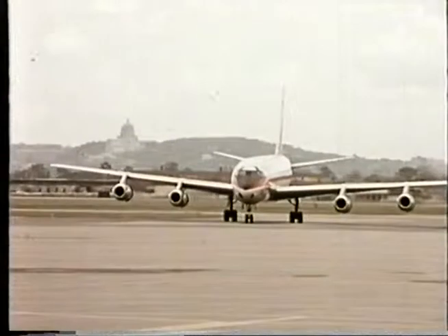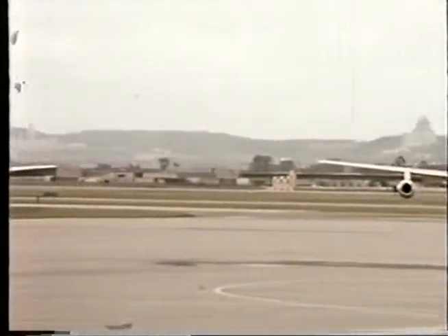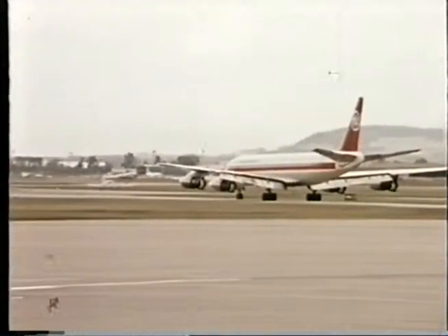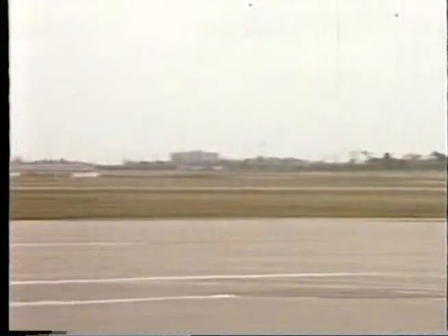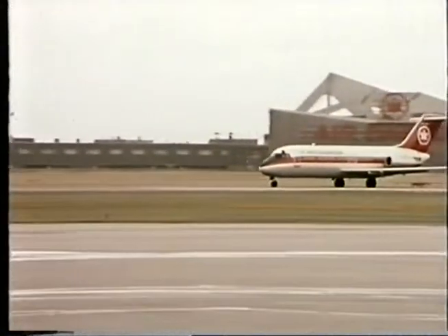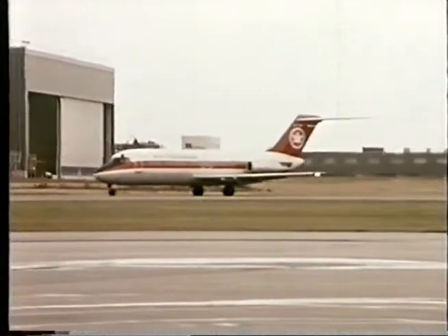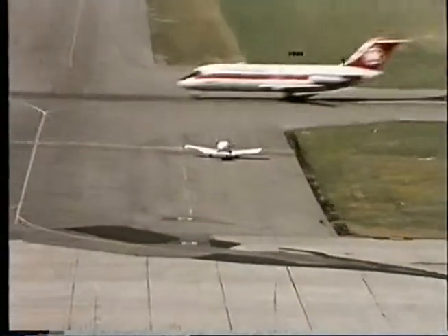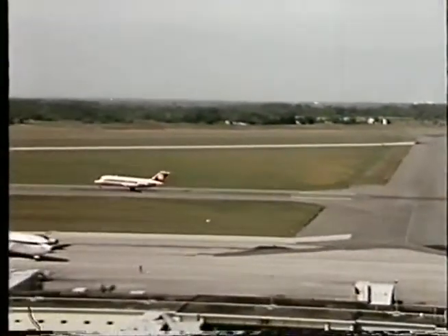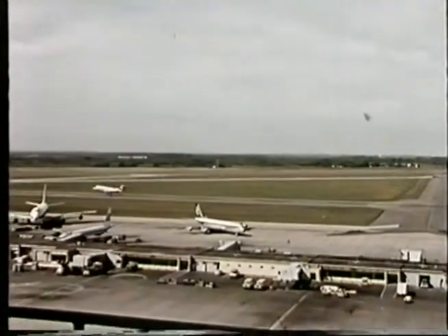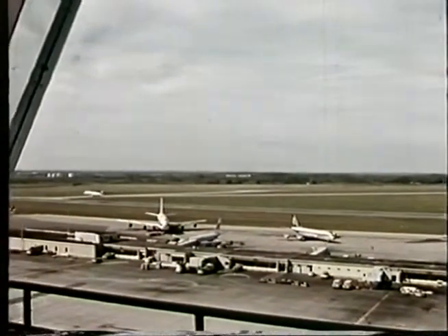If all aircraft are following the same route, it may be preferable to clear several jet aircraft for takeoff before a slower piston-engined or small aircraft. The jet aircraft climb rapidly and soon clear the lower levels.